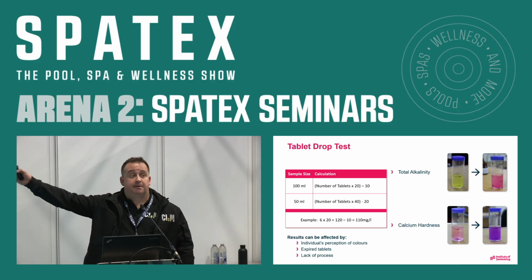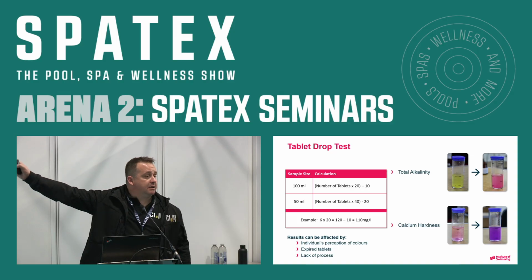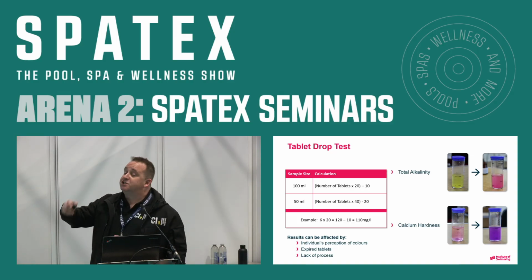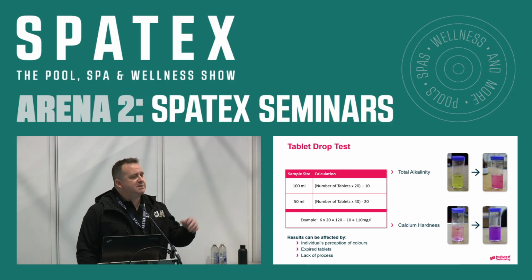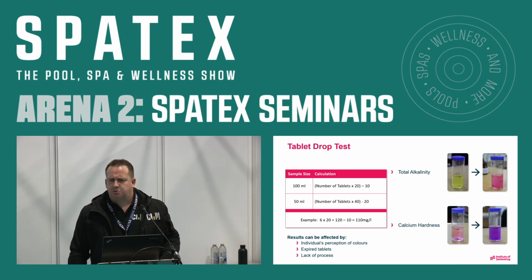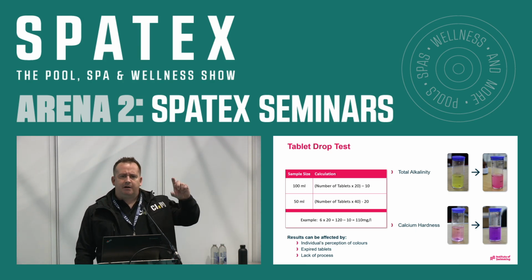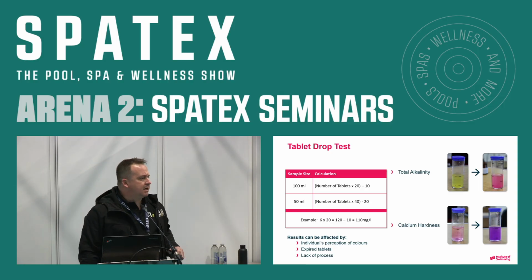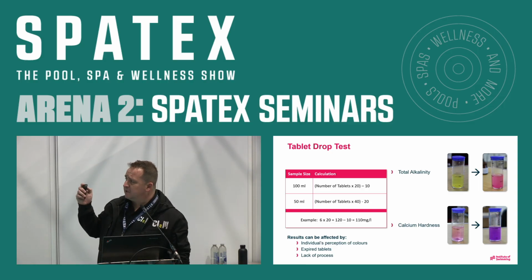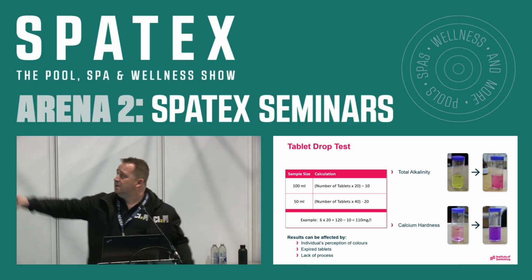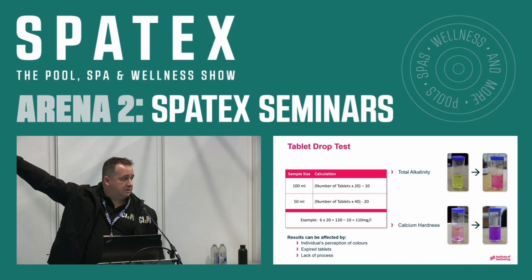This again, if you're colourblind, not so good. So cover yourself from that. Check the expiry of the tablets. Make sure you're using the right tablets. Don't use photometer tablets or comparative tablets. These are their own specialist tablets. They normally come in a little brown glass bottle, as a rule. Okay, and known process. And always remember, put the lid on it before you start shaking it.